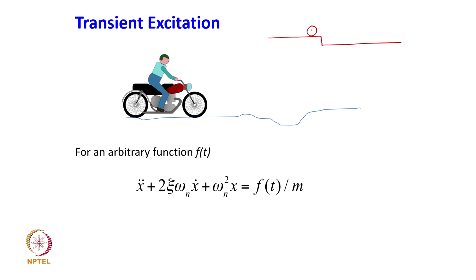For example, in the case where a simple single degree of freedom system represented either a vehicle or a crane, the sudden disturbance in terms of either initial velocity or initial displacement happened instantaneously at t is equal to 0. Okay. So, in this particular example, the initial displacement of the mass happened at exactly t is equal to 0, or at an instant of time from which the vibration response is to be obtained. So, there was a step change in the conditions, whereas when such excitation happens over a reasonable period of time, it is not an instantaneous excitation that we are talking about, but excitation lasting for some short duration. Okay.